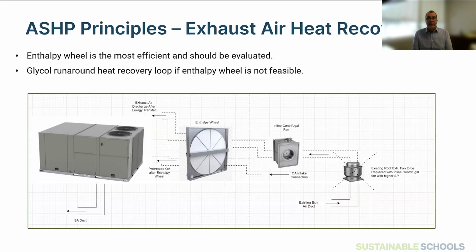We are noticing a significant reduction in gas consumption. Should point out we also eliminated boilers from our elementary school design. So, the schools that we're building now have 9 rooftop units for all the perimeter spaces and the gymnasium. The central core is heated with VRF technology, but the rooftop units do have air source heat pump potential as well. So we're running those, and we've compared the consumption of the brand new schools.